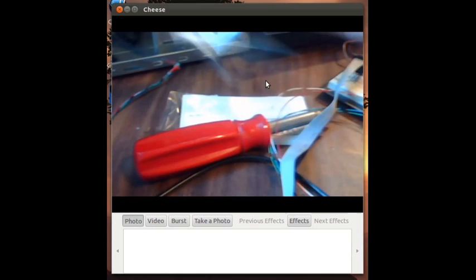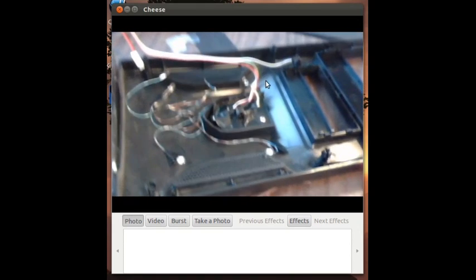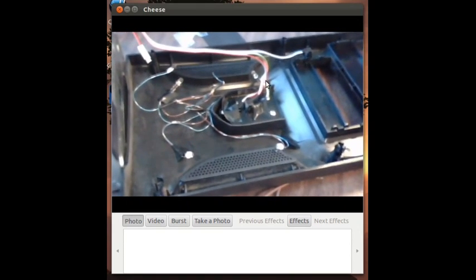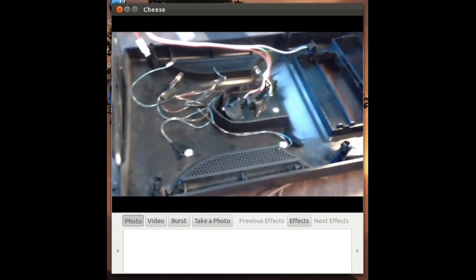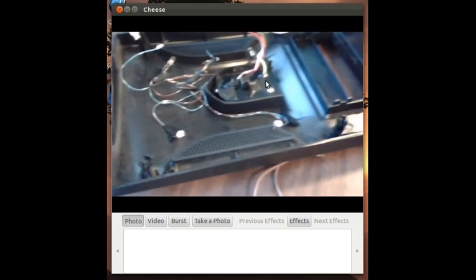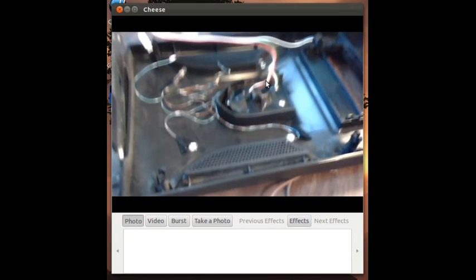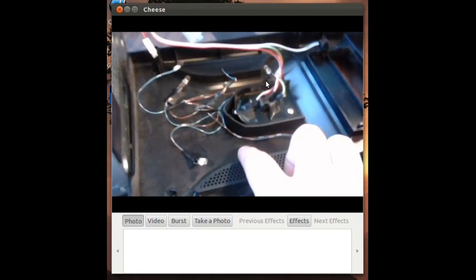Aside from the parts on the board, I also have some half watt 15 ohm resistors, which I'm going to use to replace the quarter watt resistor that is running these 4 LEDs right here. This was my previous case mod, the bland static white LEDs shining through my fan grills. So these are going to be augmented by placing the color LED right here in the middle.